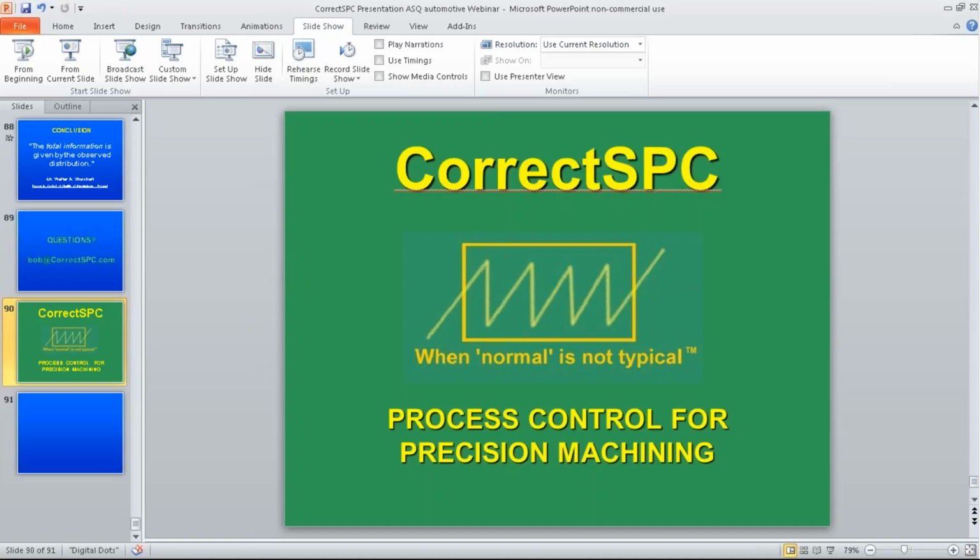And I've even talked to some places that make the machines that are using the auto compensation, and some of those guys don't even know what the algorithm is because it comes from a different location. It's not the place where they're actually trying to set up the machines. It becomes the process is all I'm saying. And so things like wheel wear, if you're doing auto compensation on a grinder, wheel wear, when to make any type of operator intervention to the wheel itself, you won't know that. You just have to kind of guess because it's all masked by this constant adjustment.